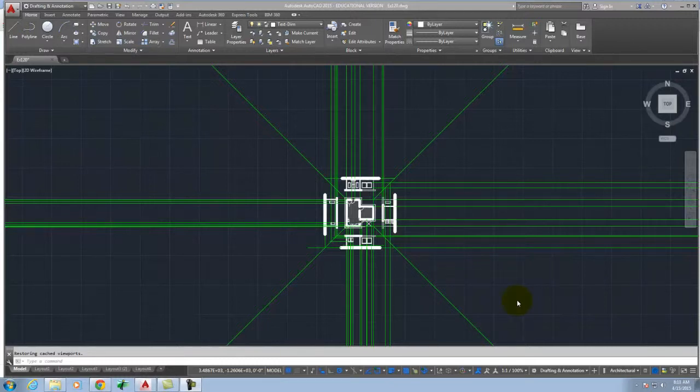So today's actually a really important concept to understand in the world of AutoCAD, and that is that there are two different kinds of spaces that we work in in AutoCAD. And thus far, everything that you've done is in model space, which basically means that it's full-size drawing, right? We draw a wall. It's 6 inches thick. We draw it at 6 inches thick. So there's no scaling involved. There's nothing other than you draw everything full size.